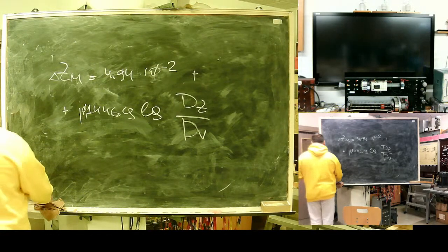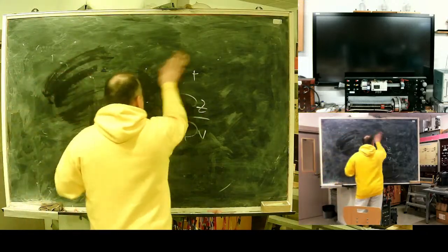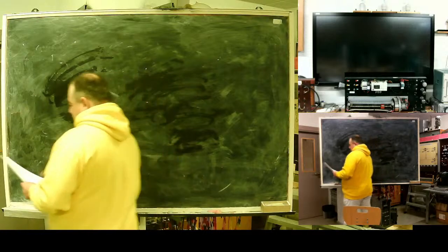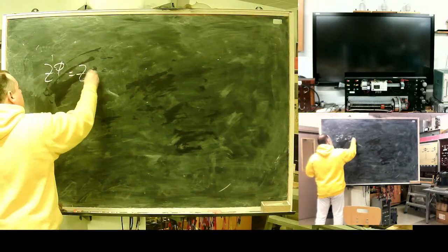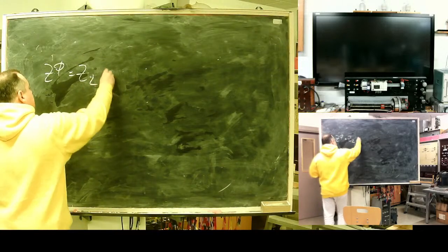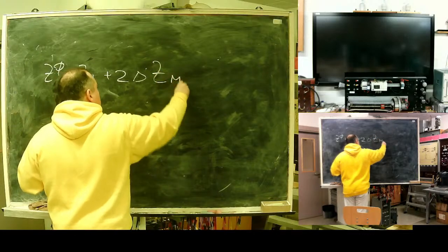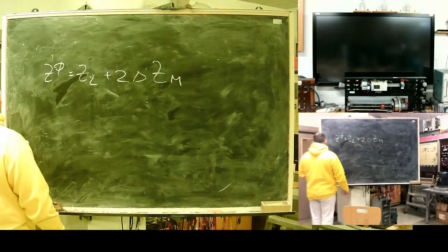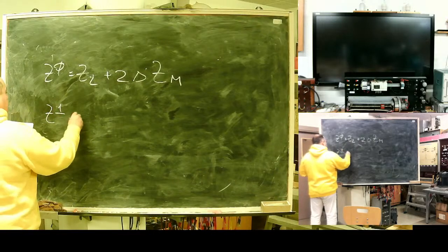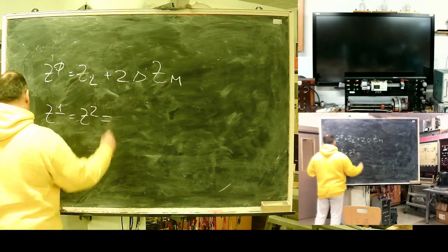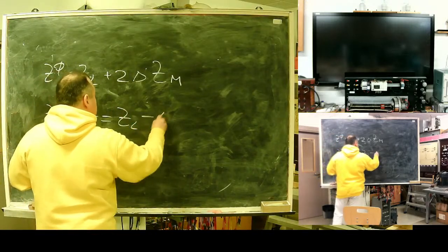I can write what? Zero sequence will be line resistance plus double mutual resistance. Direct sequence will be equal to negative sequence and will be line resistance minus mutual resistance.